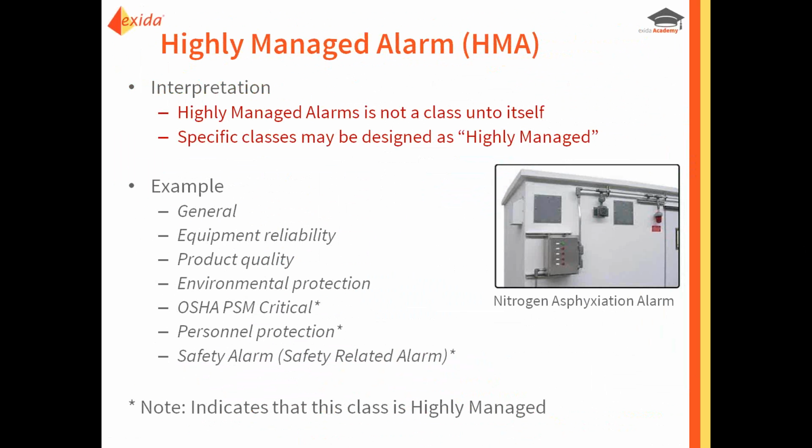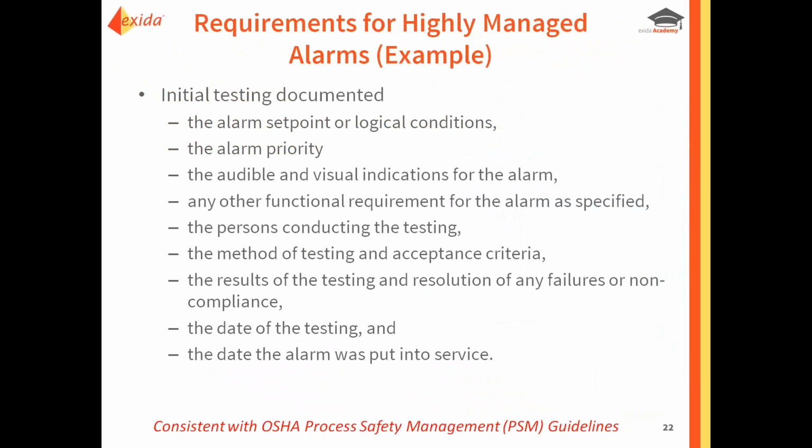But if you think about its importance and what it's for, I would hope that you would agree that it makes sense that those more rigorous requirements should be applied to that particular alarm. So if we thought of it as a highly managed alarm, the alarm for the low oxygen environment, requirements such as this related to initial testing and everything that should be documented, that the operator's response to the alarm is correct, the priority, etc., you would think might make sense for a specific subset of alarms. So the subset of alarms that are classified as highly managed would need to follow these requirements.